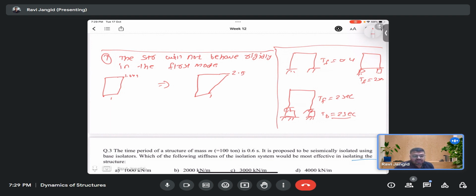Another point is the first mode damping. In the previous case, the first mode damping we got was 9.65. But when you do this, the damping for the first mode will come out to be around 4.5%, which has a larger difference from the 10% damping of the isolator. This is because the superstructure also plays a role, playing a large part in this. So that's why it has the larger gap between the dampings.